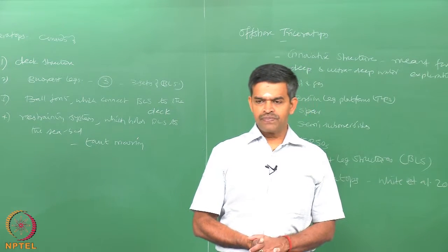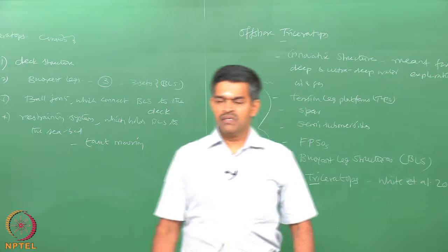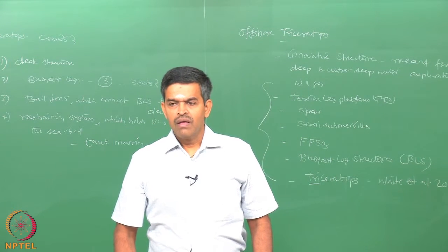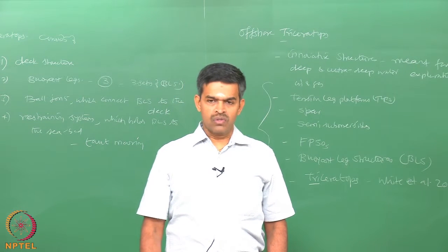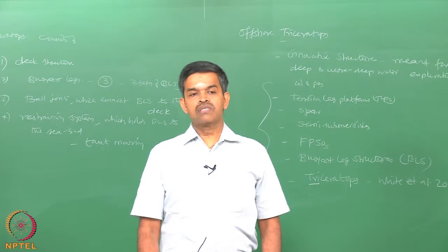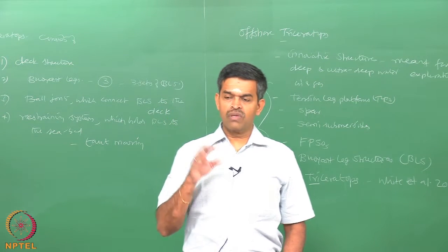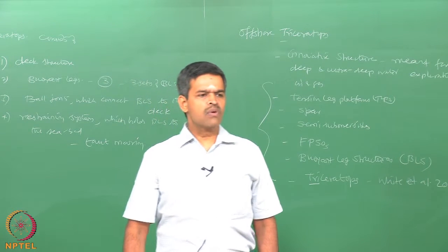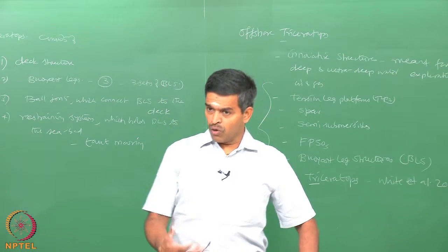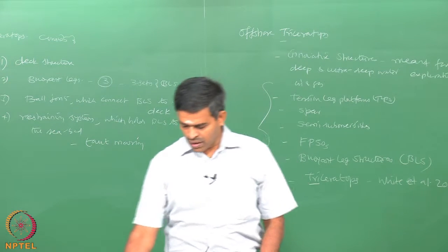Interestingly friends, when the impact loads are imposed on the BLS, since BLS is isolated partially from the deck, these impact loads can only cause damage to the buoyant leg structure, which is not transferred to the hull. Therefore, the hull or the deck remains safe. So, this can be seen as one of the interesting advantages of accident failure modes of a triceratops, which is essentially recommended for ultra deep waters.